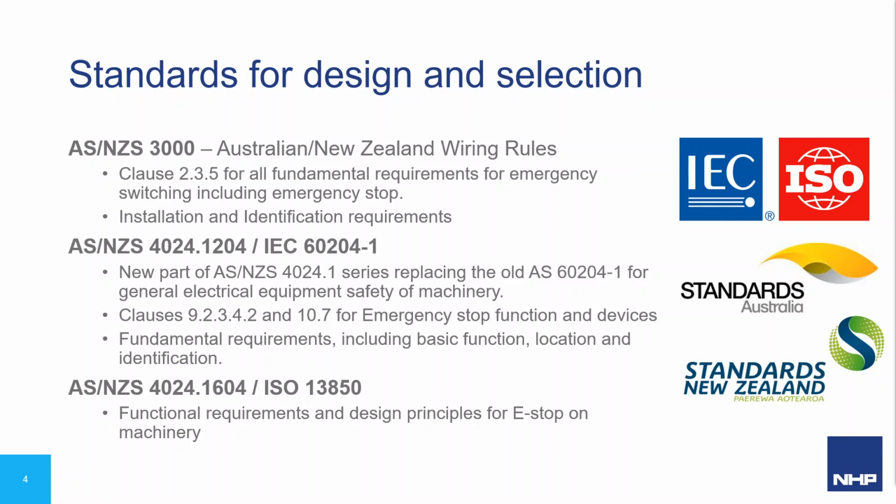What I aim to do in this webinar is to combine the requirements of each of these three standards, AS/NZS 3000 included, into an overarching framework of how the emergency stop function is realized for machinery and which satisfies the requirements of all three of these standards.